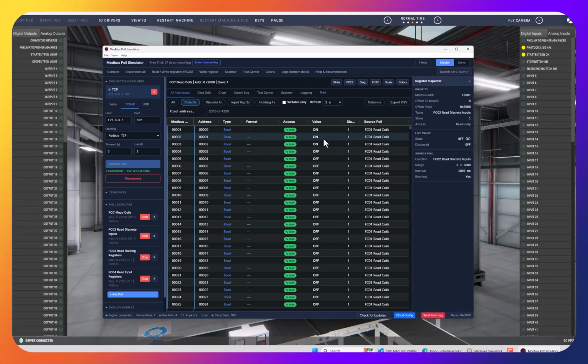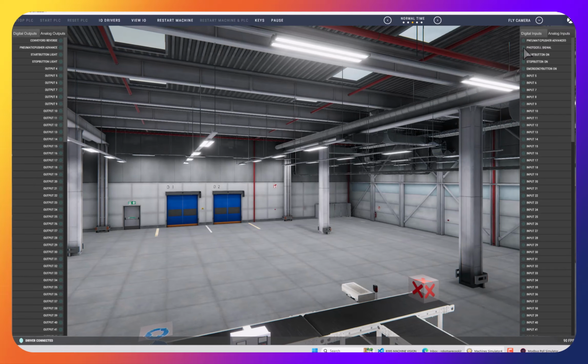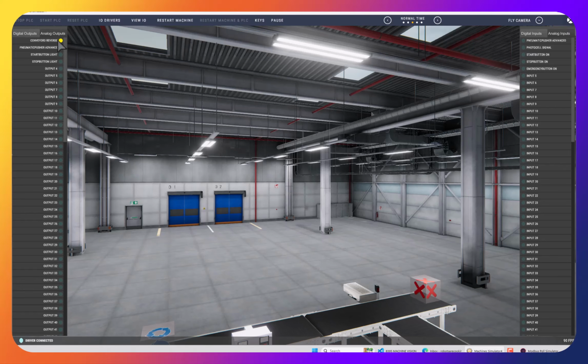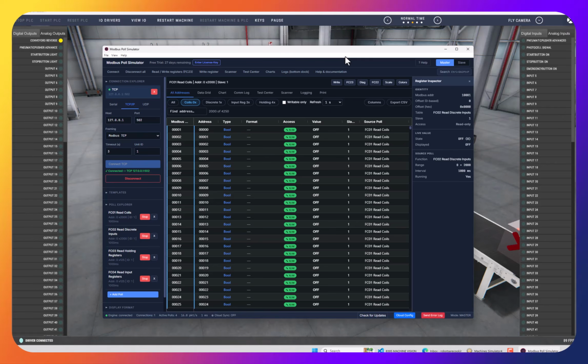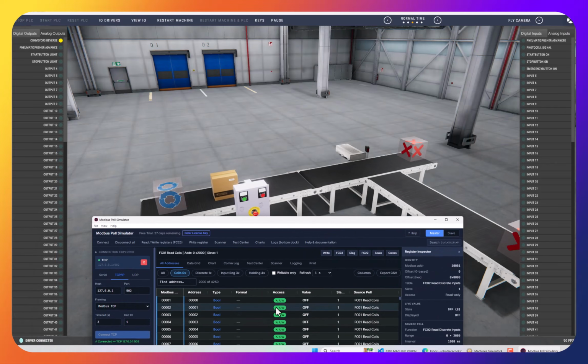Right now there are 2 inputs here. And if I go ahead and actuate the output and turn on the conveyor, you will see that this input here, when this LED photocell looks at the box, look at the inputs here. Boom, turns on. Good. So we have good communication. We've got everything, but I have no idea how I can turn an output on and off.